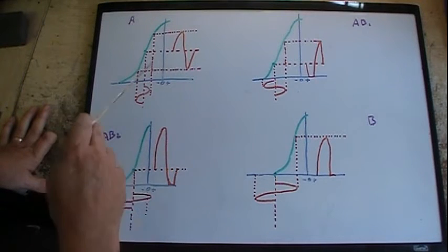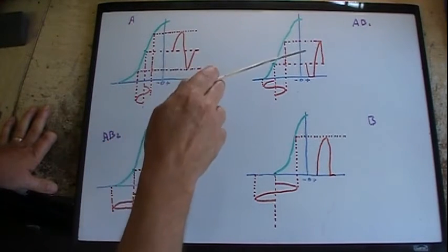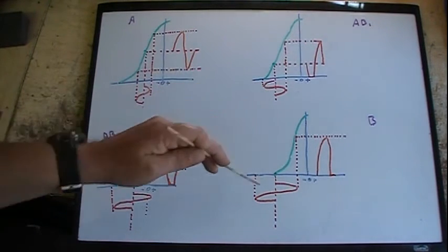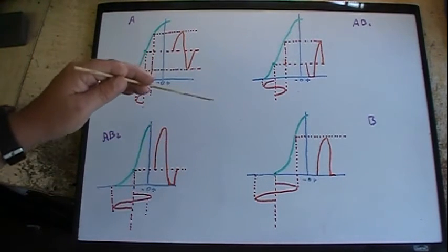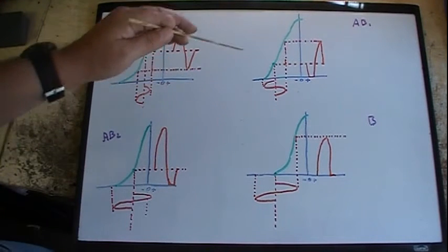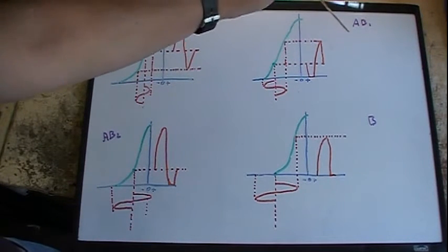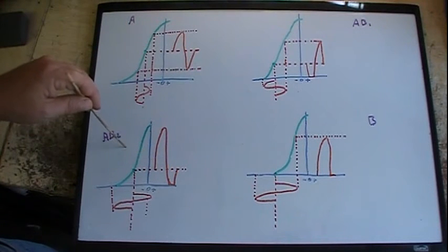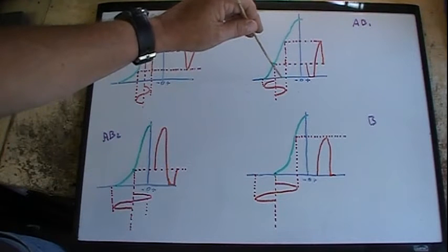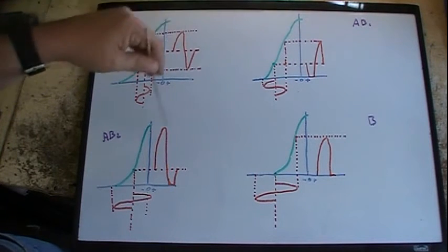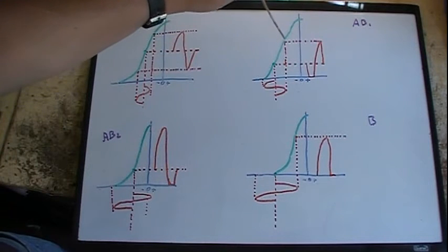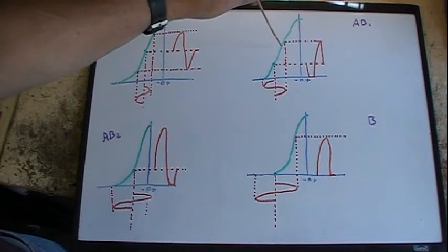So in between these two, we have Class AB. Now we're going to come back to this in a minute, but with Class AB, I got pretty much all of it on here. It's broken down in two sections: AB1 and AB2. In both of them I set the operating point somewhere between cutoff and the linear portion, center point anyway,